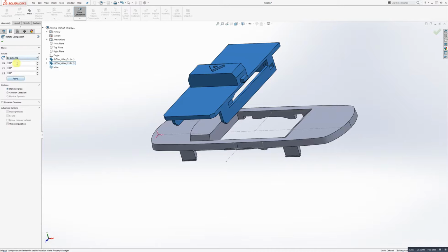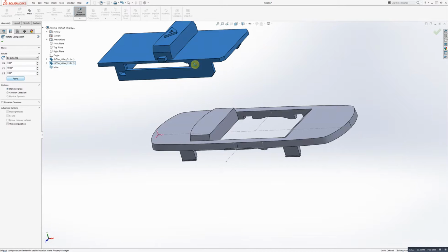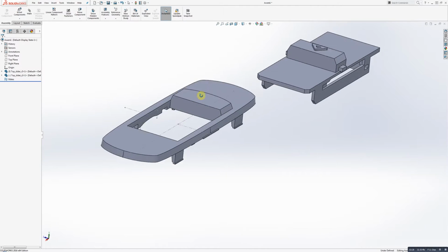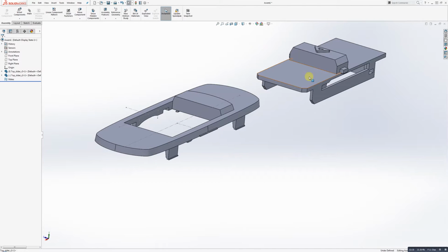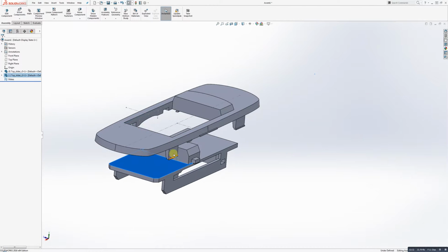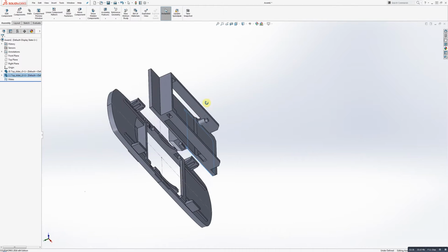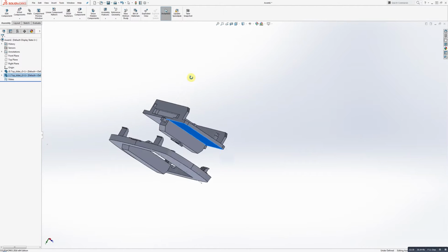So I'm going to go here to rotate. Okay, if this is sucked up like that, you got to open it up and go rotate, go Y, and then go 90 degrees. Okay, and then just hit apply, and it's going to flip right into position. All right, there we go. So we're getting these things in near each other. All right, so I'm going to bring this guy down a little bit closer, and actually I'll flip it up like this here, and we'll kind of get it orientated.